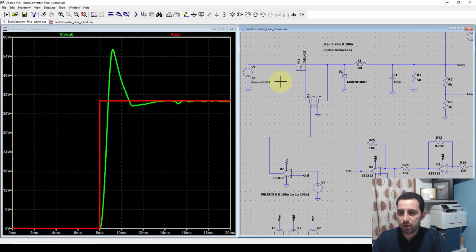Now, as I mentioned before, we have unticked this option, and I have seen some people get stuck with the simulation when we run it. I will run it now. Look what's happening at this corner here. It says stepping, and now stepping source, and it achieves 100%. So it finished the 100%, but it says here press escape to quit. So what you have to do, if you have got this message, is just press escape once, and once you escape the first time, it jumps to another run for another stepping, and now it reached 100%.